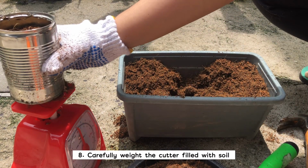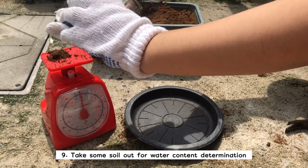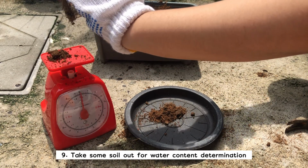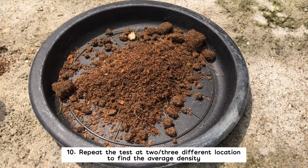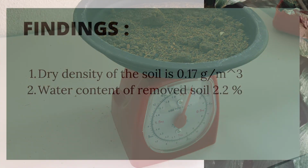Then, carefully weigh the cutter filled with soil. Next step, take some soil out for water content determination. And then repeat the test at 2 or 3 different locations to find the average density.